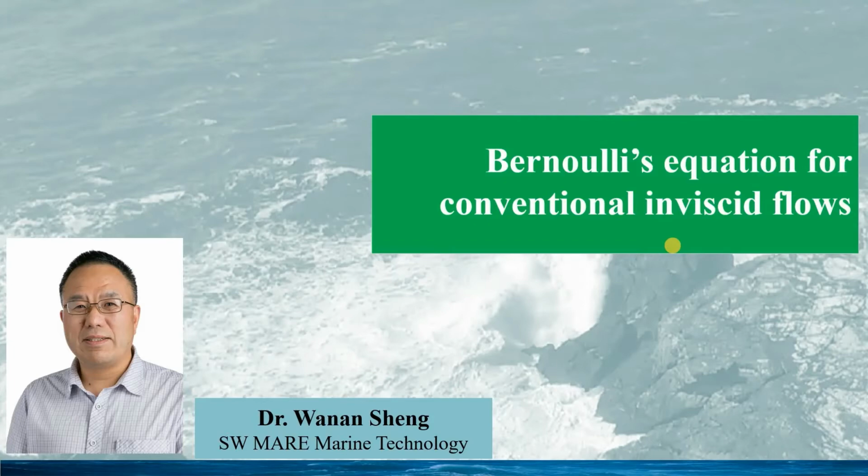And we will also see in deriving the conventional Bernoulli's equation, some assumptions must be applied. For instance, the conventional Bernoulli's equation is only correct for steady inviscid flows.